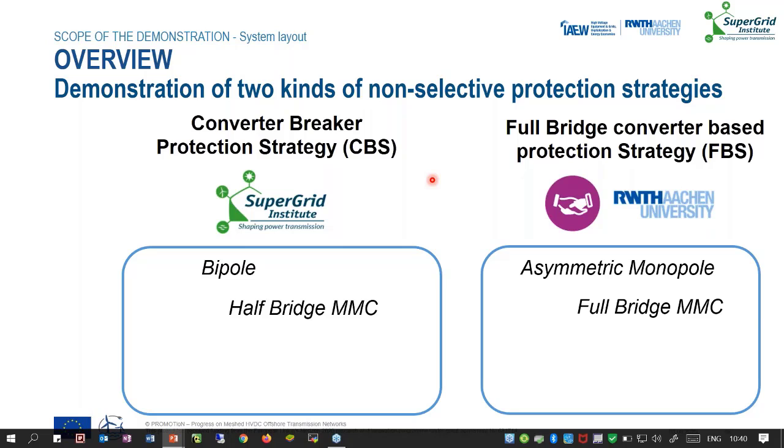The second one is the type of MMC converter. For those not familiar with this, the main difference between them is that half-bridge converters cannot operate during a DC fault and will block, while the full-bridge converter can indeed limit fault currents without blocking its operation.